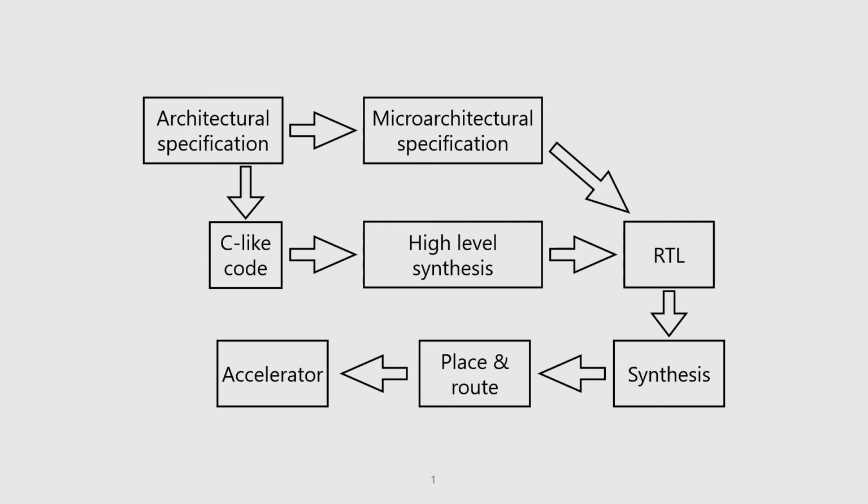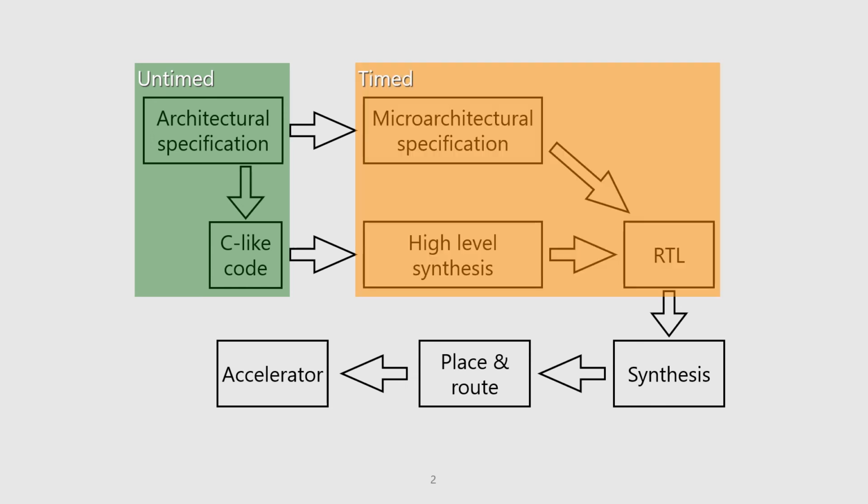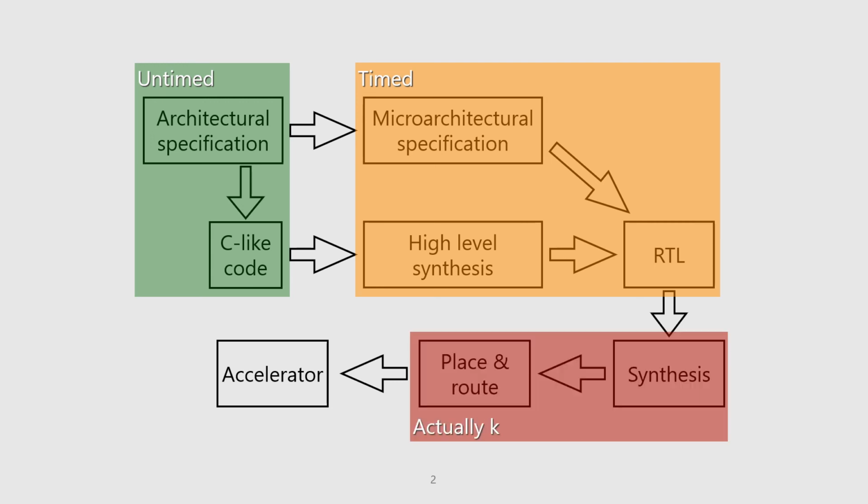new accelerator. More to the point, we start with this untimed representation. It's unscheduled, it has no notion of clocks, and then in the microarchitectural phase, we schedule it. We add precise timings to our pipelines. But then we hand it off to the tool, which actually knows about time. We don't know how long signals take to get around the chip until we hit place and route.